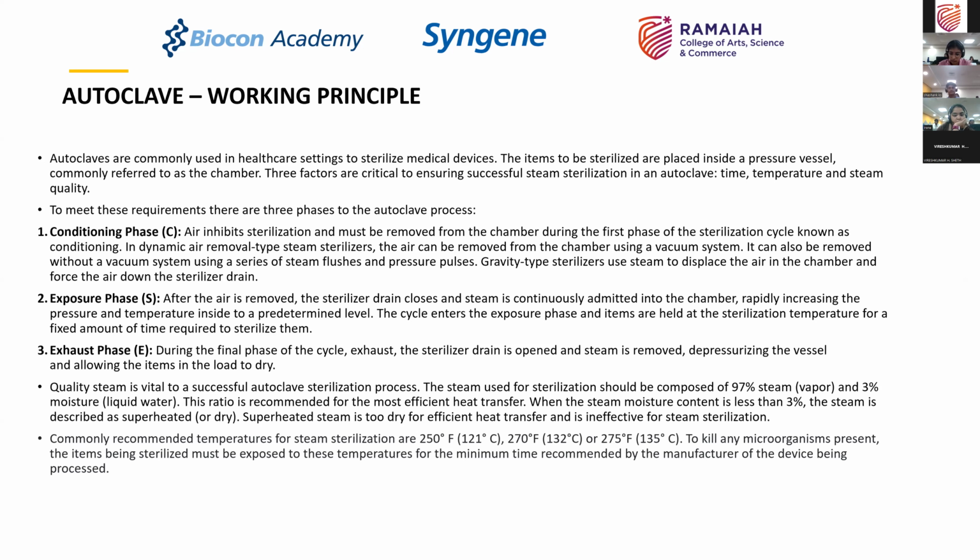As we said, in dynamic type steam sterilizers, you remove the air from the chamber using a vacuum system, or it can be removed by giving a series of steam flushes and pressure pulses. So you introduce steam into the chamber, allow it to dwell there for a certain time and push the air out, and then keep on doing pressure and steam pulses, pressurizing the chamber using steam flushes so that the air gets displaced.